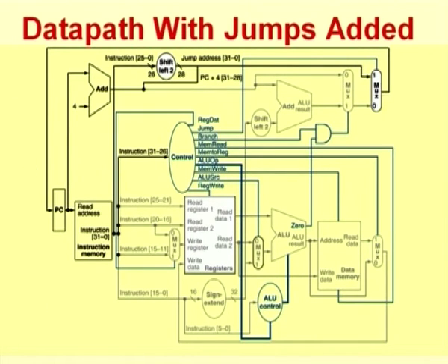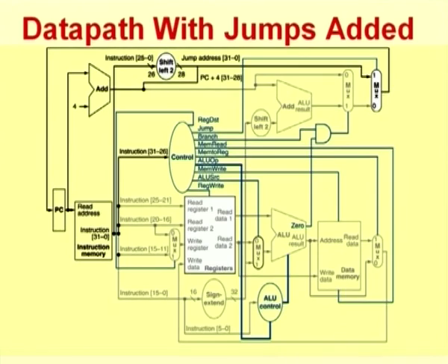What we have assumed in this entire discussion is that this whole thing takes place within one clock cycle. Okay, that was our assumption. So, within one clock cycle, all these things will get done for every instruction. Because different data paths are highlighted for each different instruction, the time taken may vary for each instruction. But if we assume that the whole thing takes place in one clock cycle, then whichever is the longest instruction will determine the duration of the clock cycle. So, that would be our assumption for the simple design.